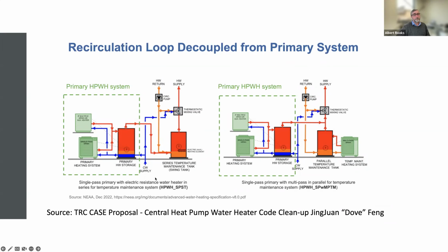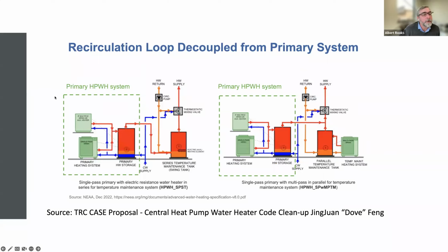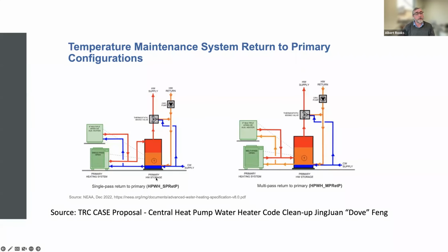I'm going to go back there and note this box up here is multiple heat pump water heaters or an auxiliary heater, because we could do that too, right? We could put a bunch of heat pumps in series, and then throw massive amounts of electric resistance heat in it also to do some additional lifting.